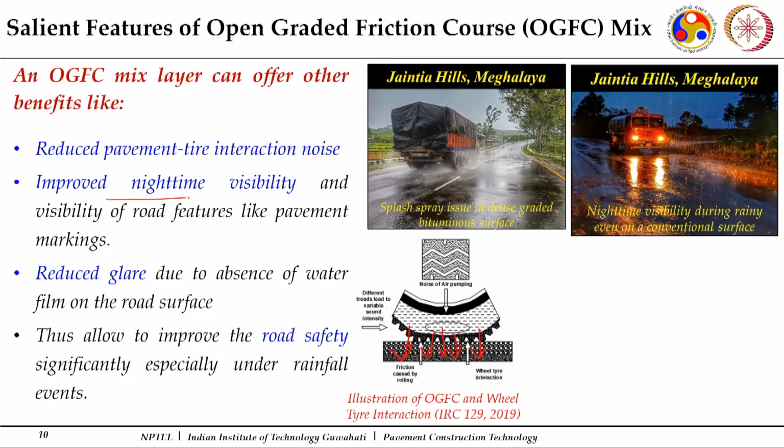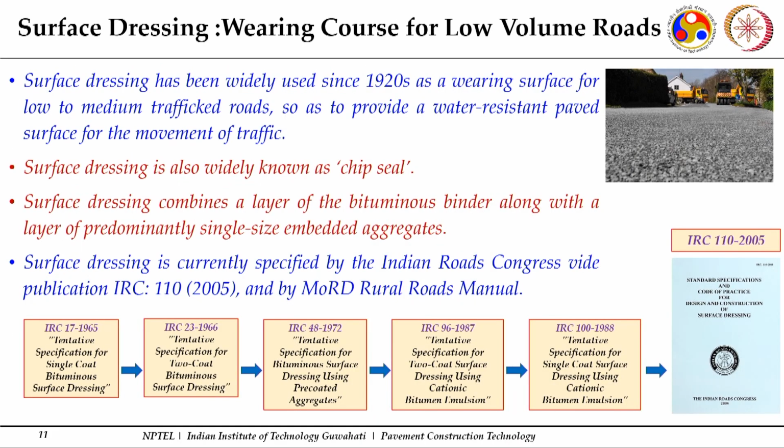So, we can see that since the glare is reduced, splash and spray is reduced, so you get good nighttime visibility. With this visibility and reduced glare, road safety significantly improves, especially under rainfall events or wet weather conditions where skid resistance is significantly affected. So, these are some typical features of these open graded courses.